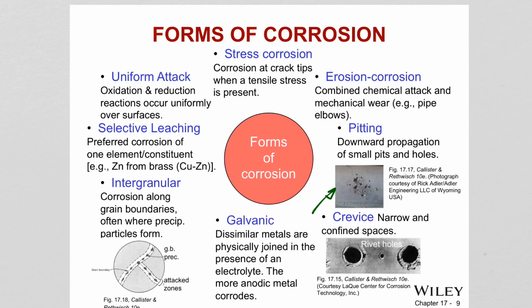Variations in the surrounding environment can cause corrosion, such as variation in oxygen content in the electrolyte, which produces anodic and cathodic regions along the surface. An area low in oxygen will be anodic to areas high in oxygen content. In practice, variations in oxygen content are associated with crevices under bolt heads and rivet heads. That's why it is called crevice corrosion.